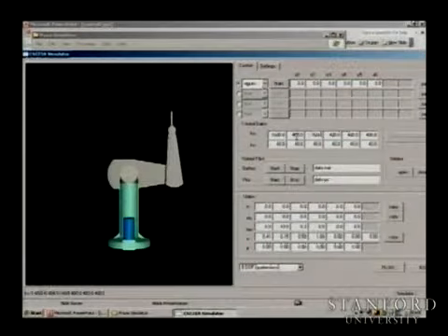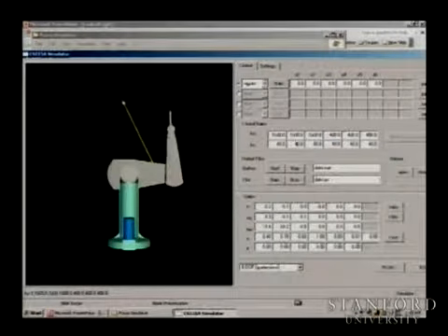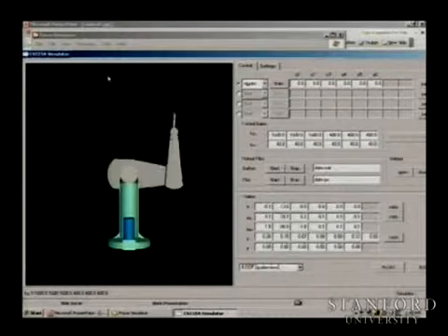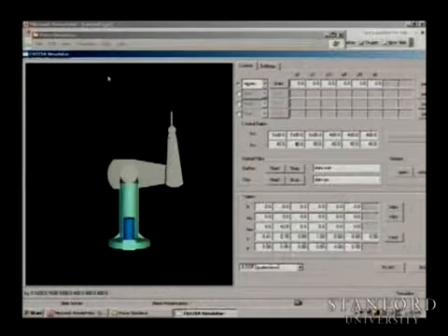In fact, if I increase joint 2 as well, it will be hard to move it. So what is happening now with the response? Do you see the response when we went to 1600? Faster or slower? Faster. So the dynamic response of the closed loop is faster with higher gain.